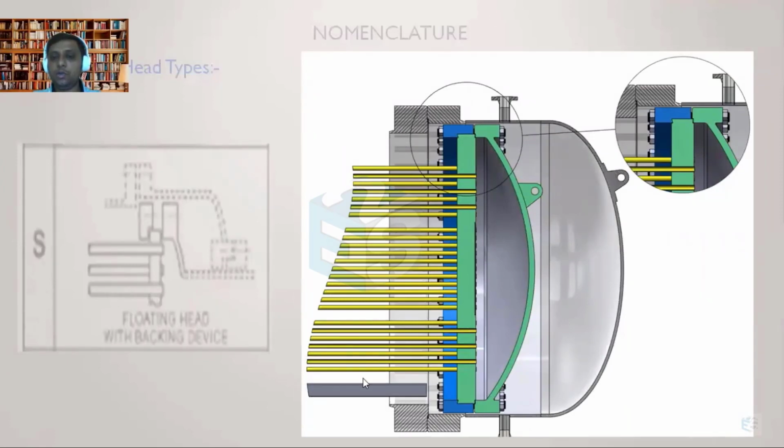So these are the tubes. This green one is the tube sheet. This green one along with this flange represents the floating head. This blue colored one represents the split ring. How this assembly will work, we are also going to see in a 3D animation. We have already seen in detail, in the video on this AES type of floating head construction,